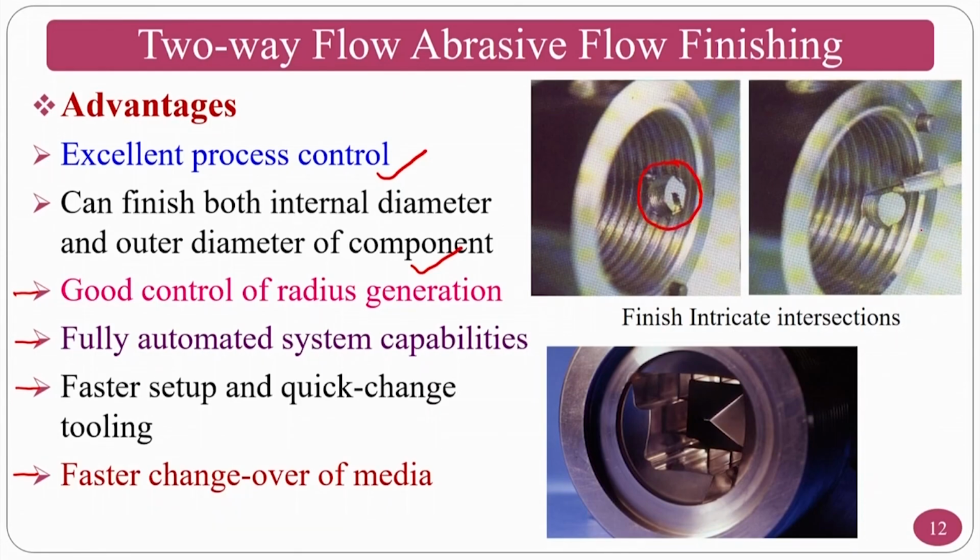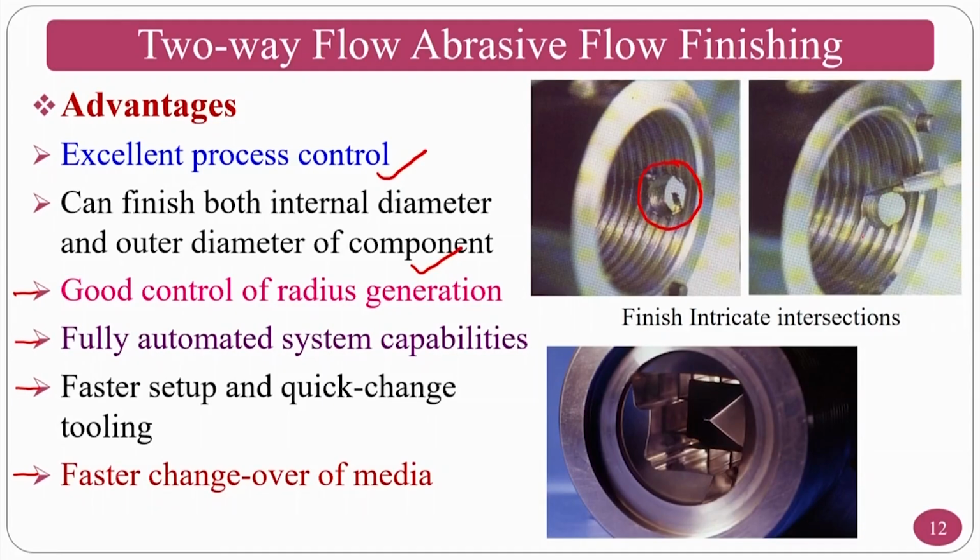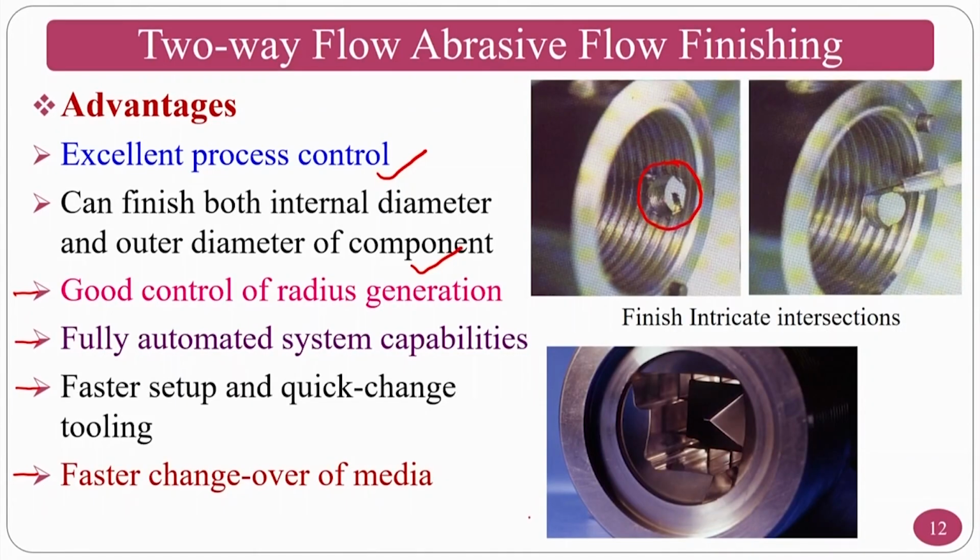However, this deburring also can be done by thermal based deburring processes. For that purpose, if one has to go for this type of deburring process, you have to have proper tooling. The bottom one can be finished by the abrasive flow finishing process. However, for the top one people normally prefer thermal oriented finishing processes for deburring applications, and you have every chance to use the abrasive flow finishing process also if you can maintain the proper tooling.